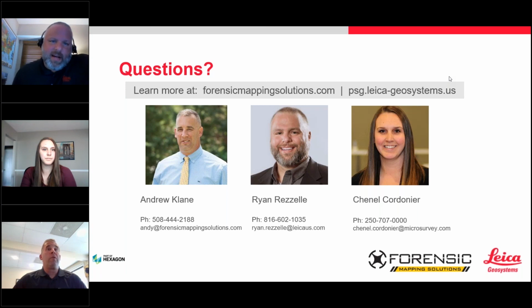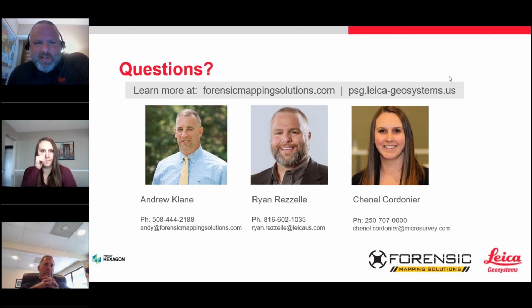Well, I could tell you, and Andy, I'll let you answer here in a moment, but with the ScanStation, I actually did this about a year ago. We had a ScanStation out and a DJI drone, and we scanned those in, and we actually created the GCPs from the ground targets in the registration software, and it worked amazing. I don't know if, Andy, that's similar to what you've done using ScanStation and DJI together, but it was quite amazing. The ScanStation can scan at such high resolution. Those GCPs were almost like a solid surface, like it had been modeled, and the data sets overlapped perfectly.